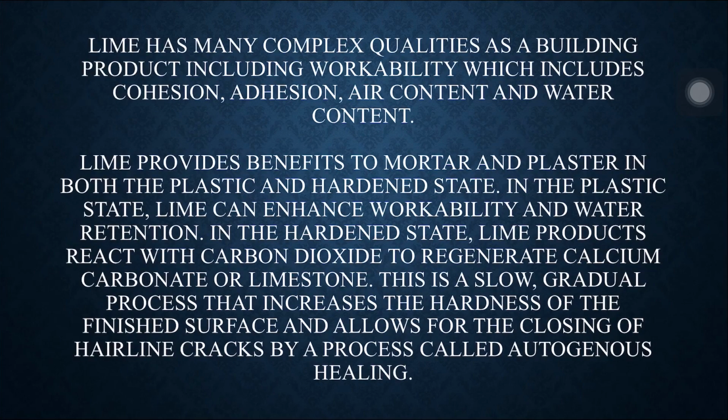Lime has many complex qualities as a building product, including workability, which includes cohesion, adhesion, air content and water content. Lime provides benefits to mortar and plaster in both the plastic and hardened state. In the plastic state, lime can enhance workability and water retention.